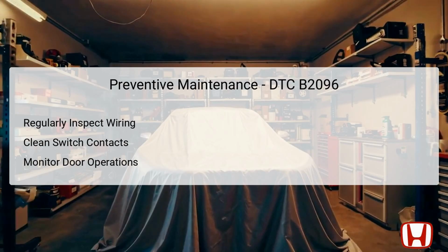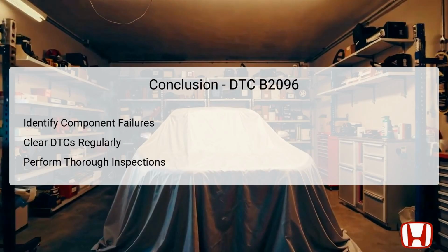Developing a routine maintenance schedule focused on these components not only enhances safety, but also improves the overall reliability of the door system. Keeping the system in good condition reduces the likelihood of encountering DTCs like B2096 in the future. In summary, DTC B2096 highlights the issues related to the right B-pillar switch and the functioning of the power sliding door. By identifying component failures promptly, it enables technicians to implement necessary repairs effectively.